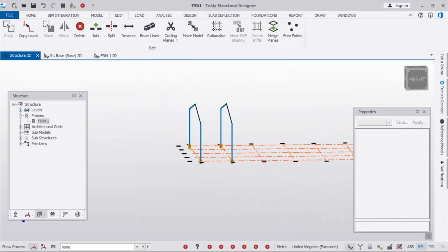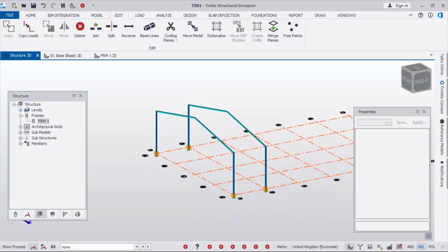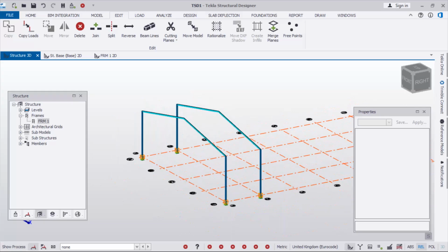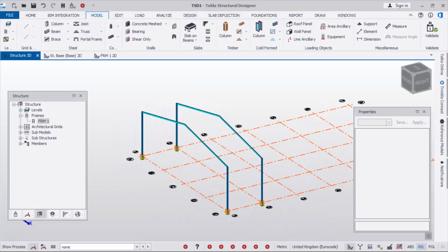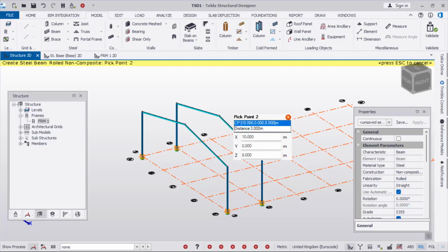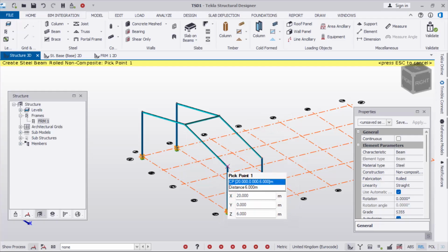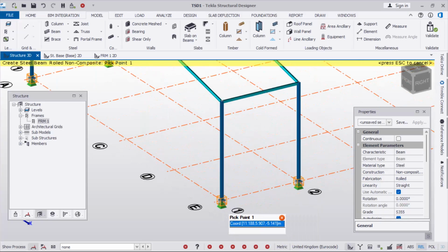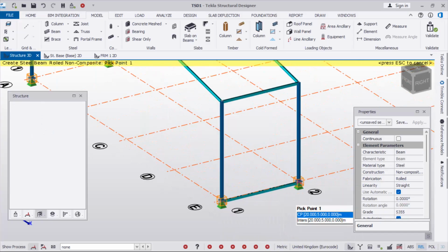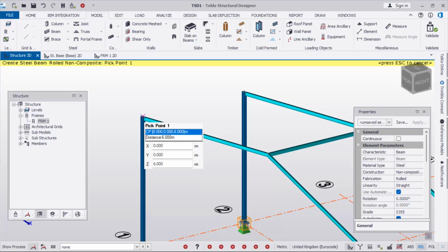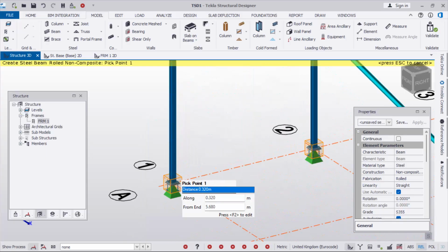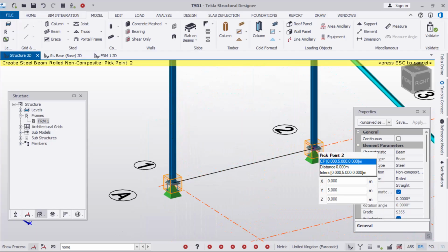And after that, what you're supposed to do is enclose your model so that you can do your slopes. And then you're going to open the slopes one by one and draw your purlins using infills. So just have a beam here, and another one here, and another one here. Then you can just add another one on this side, and you can have another one here, like that.